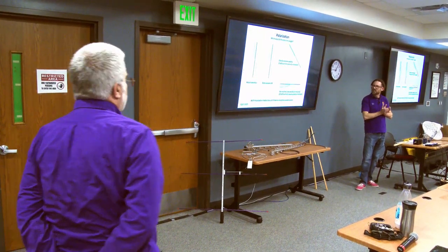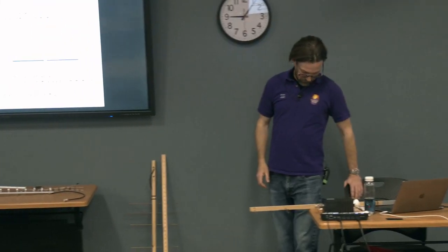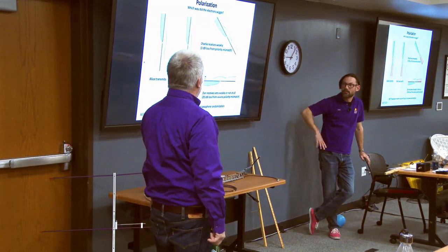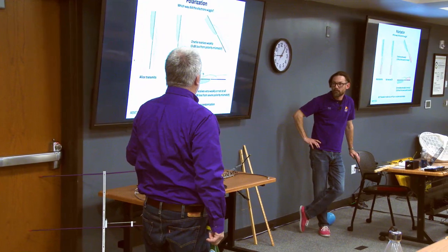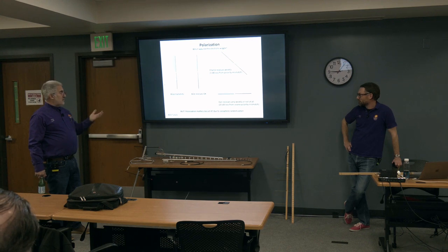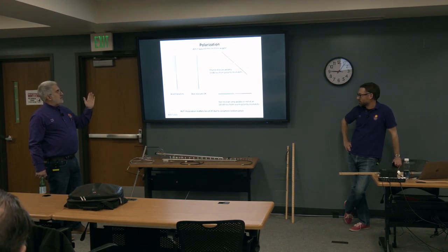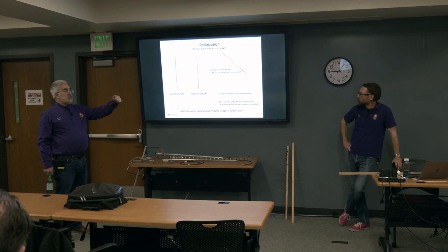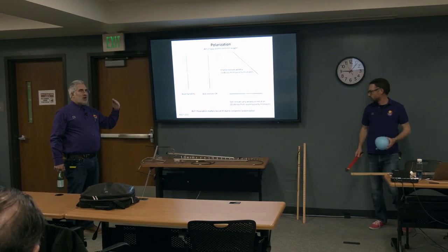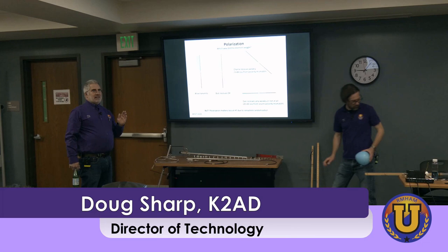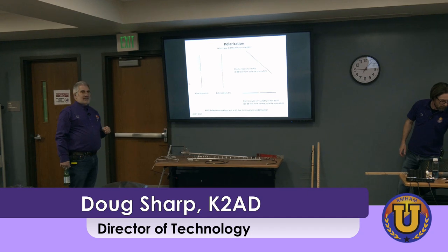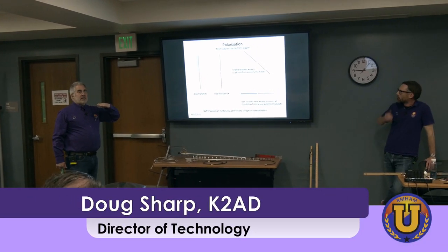Okay. What I was going to add to this is Chris did a very good job, but why is it 20 dB? And on a satellite dish, vertical to horizontal, it's much more than 20 dB. Okay. Why in ham radio and the frequencies we use? Because as this wave propagates, it bounces off things. That thing could be the ionosphere, it could be a building, it could be cars, and the polarization will tend to rotate, and it blurs. You do get a net of about 20 dB from polarization mismatch, which means if you're running